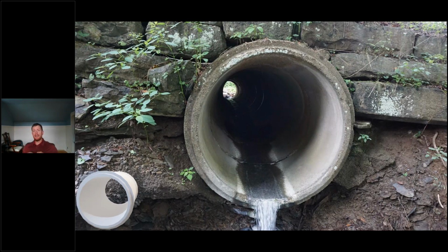So we just talked about how it's not necessarily the smoothness, what we normally every day talk about as smoothness. That's not exactly what we're looking at. What we're looking at is the straightness of the wall. So if you look down this concrete pipe barrel, you'll see that the wall is straight. And there are still joints in there. There's still some fluctuation in the total run of this concrete pipe. This piece of pipe has been in the ground for about 80 years. So there is a little bit of fluctuation. It's not a perfectly straight installation, but that's all taken into account, and that's the 20 to 30% factor of safety.